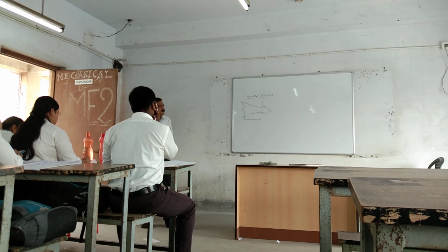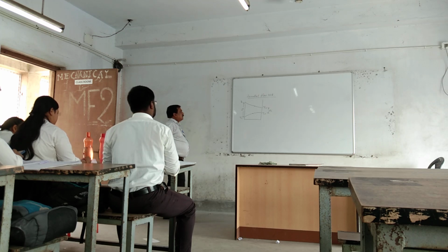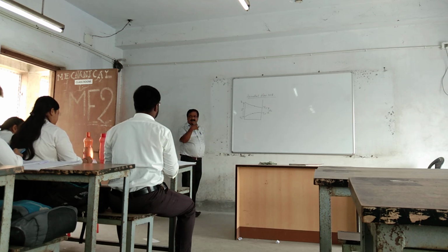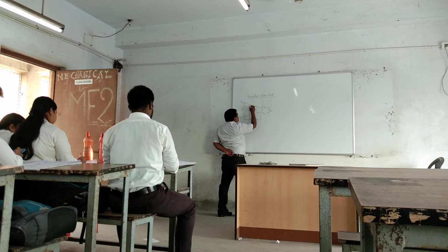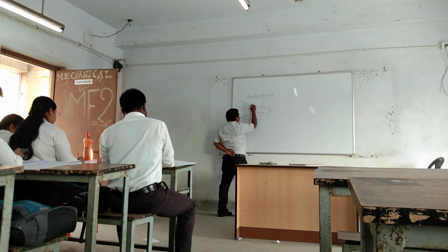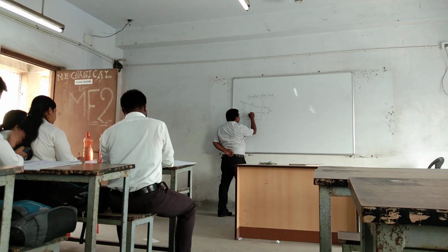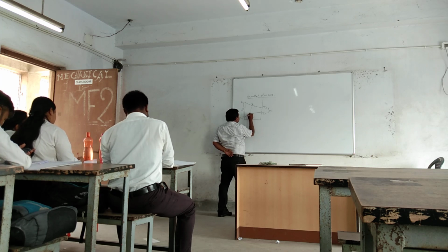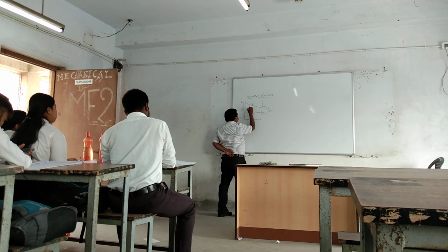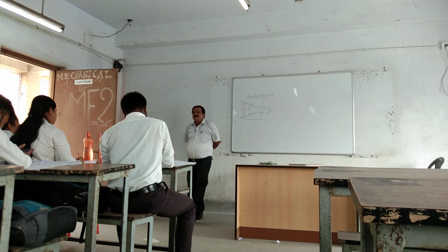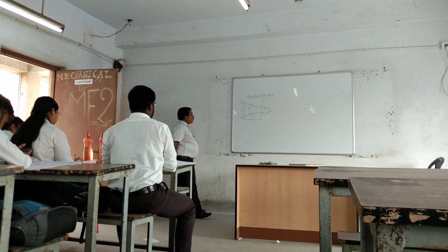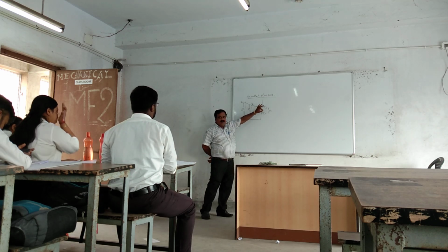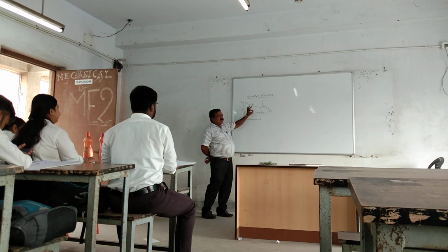So this side is delta T1, that side is delta T2. We are considering one strip where the temperature is TH and here the temperature is TC. So these two difference we are considering as, suppose, delta T. In a parallel flow heat exchanger, hot fluid is coming from THI to TH2, cold fluid is coming from TCI to TC2.